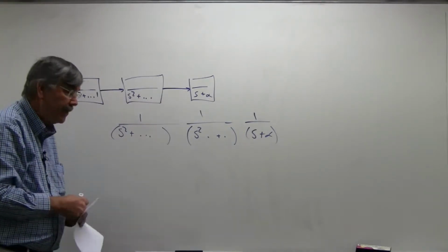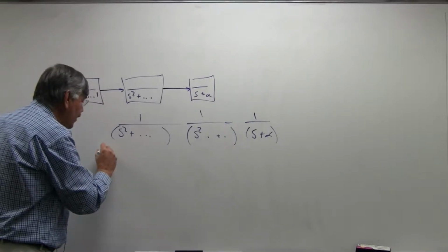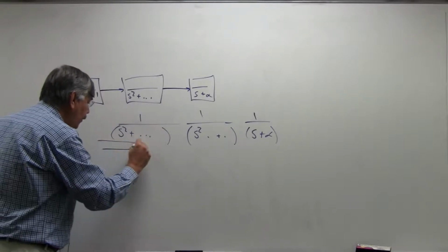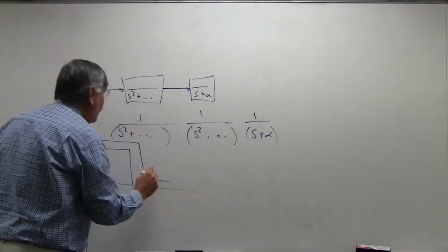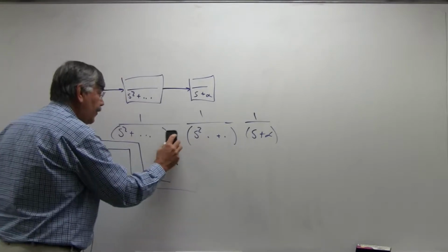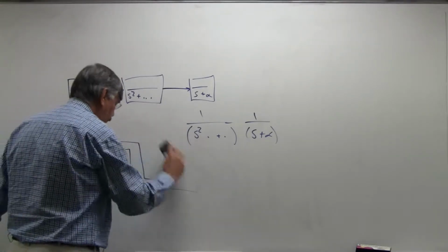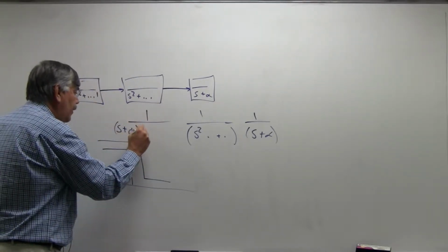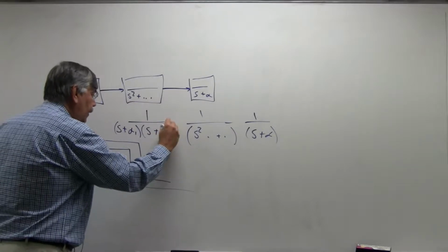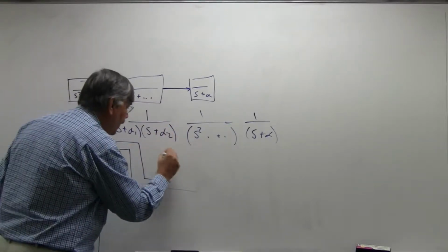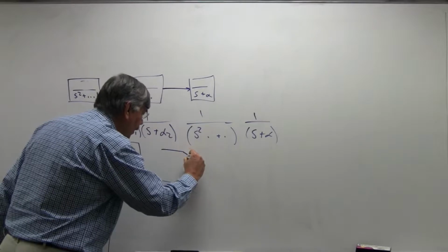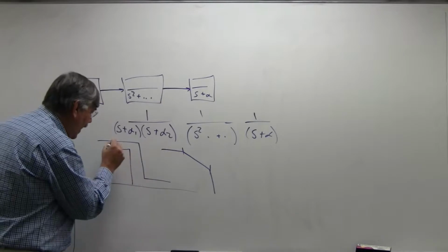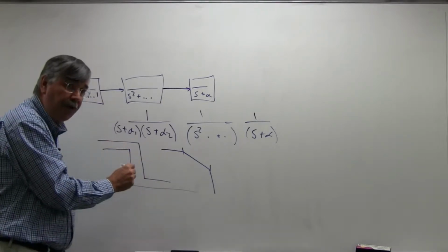I say that they're complex conjugate, I guess I should have mentioned this, that for reasonably high selectivity, if we try to use real poles, if I tried to have a factorization out here where a couple of the poles are real, so that it would be convenient to write them as s plus alpha 1, s plus alpha 2, right? The real poles, as we know, I have a different place to draw this, but the real poles will have 2 breaks like this, and it's going to be hard to not cut this corner as we go through.